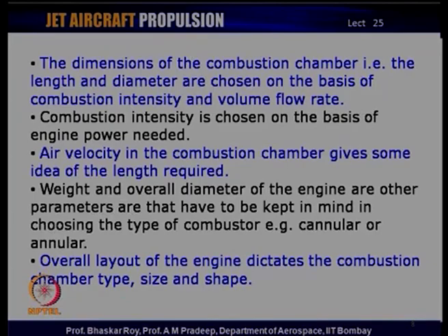The other things that we need to look at are the weight and overall diameter of the engine. Now, you may be having an aircraft engine that is necessary to be a small engine. For example, if you have a military engine, you need to make sure that the overall diameter is as small as possible, so that it fits inside the body of the aircraft, and of course, it is necessary that its weight is as small as possible.